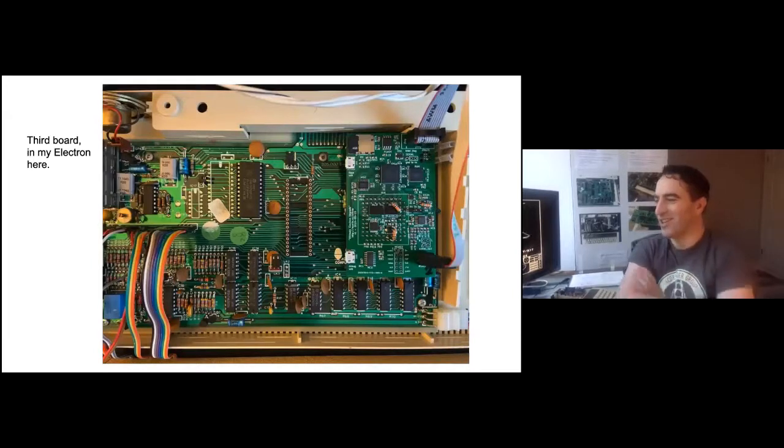So eventually I decided to go get the SDRAM working properly, figuring out all of the crazy clocking stuff you need to do to get it working at the actual rate of the FPGA. Much time learning about set input delay and set output delay for FPGA people. So yeah, this brings us to early December last year. I pretty much haven't touched this project since.